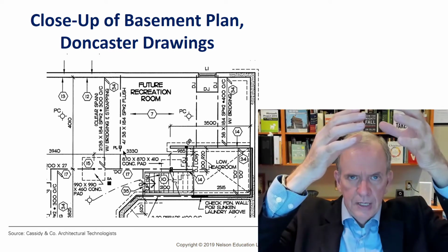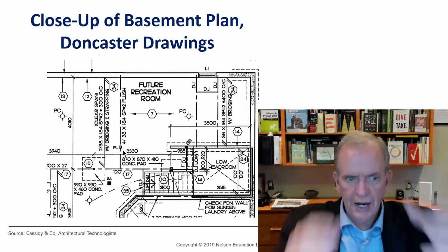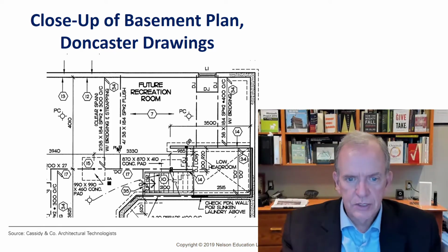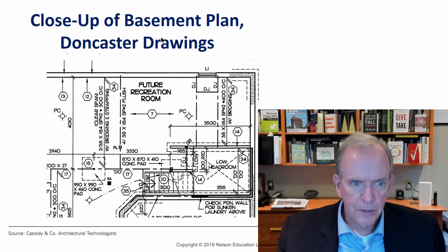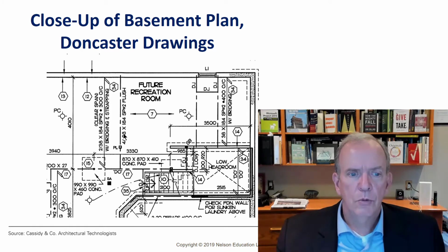So it's actually some jack studs that are supporting a lintel over a doorway, and it kind of comes down in the middle of nowhere over this floor. Well, you wouldn't want that column just coming down on the subfloor, because that would sag. So we put a beam in the actual floor, a built-up wood beam, and that's acting as protection or transference of that load to the actual built-up wood beam.